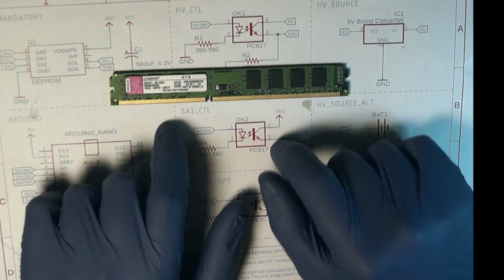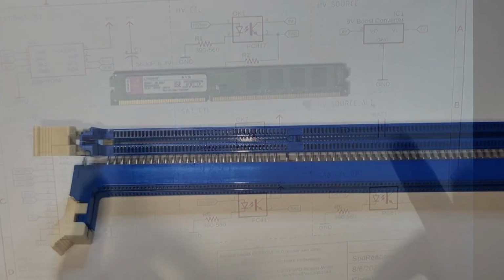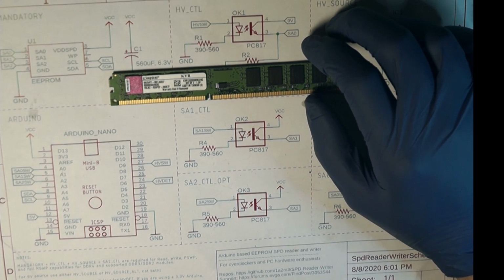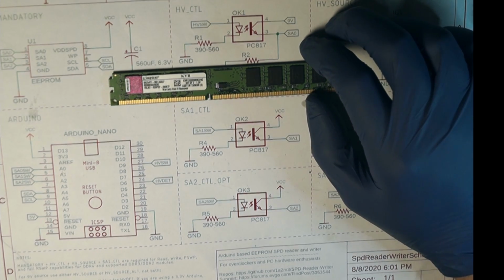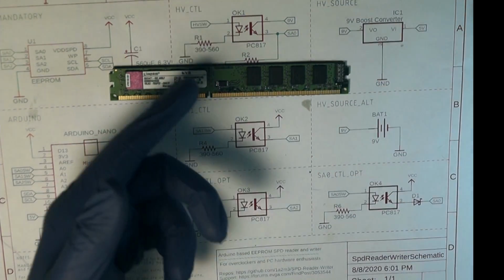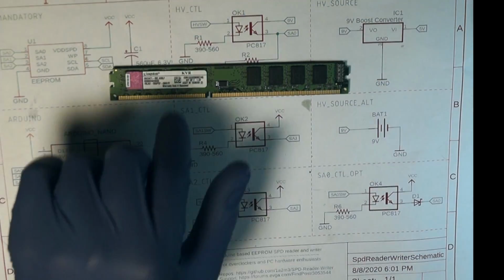Personally, I didn't want to solder to these pads because it doesn't look clean or nice, but it's definitely possible. It's also possible that you can buy a DDR socket and then solder to the pins of that socket. If you want to do this on a regular basis, this might be interesting to you. Personally, I don't plan to do this on a daily basis, so I'm happy with more work when you have to solder to the PCB.